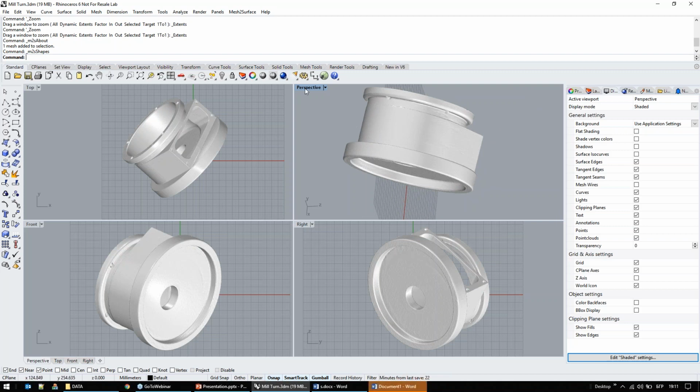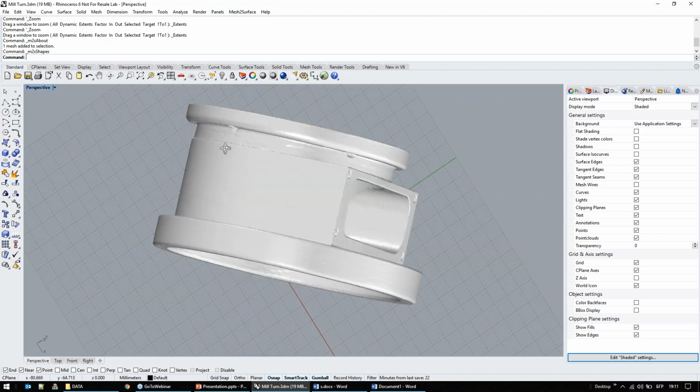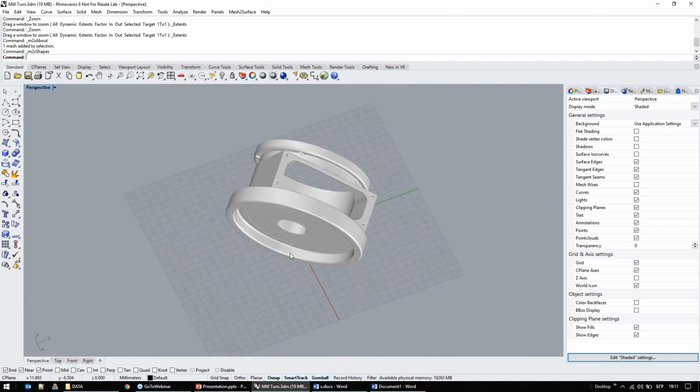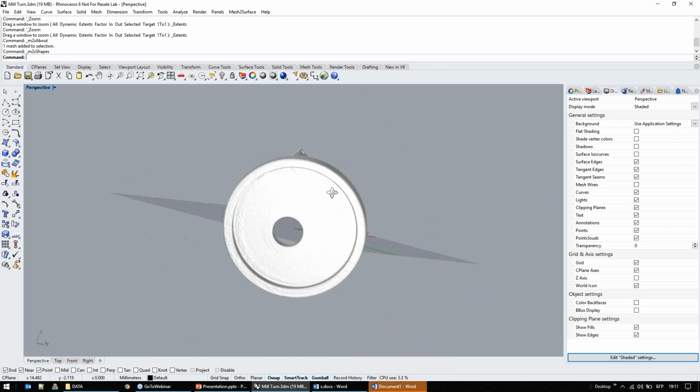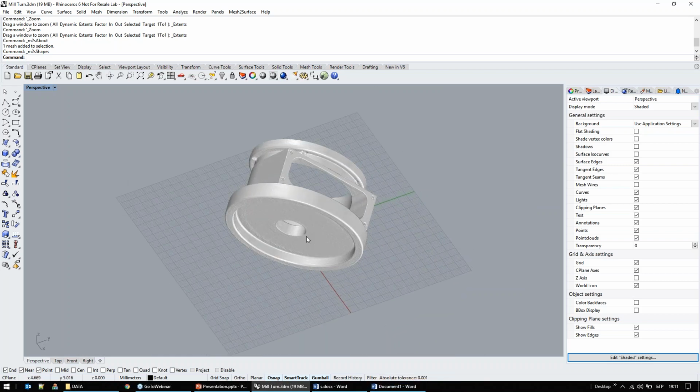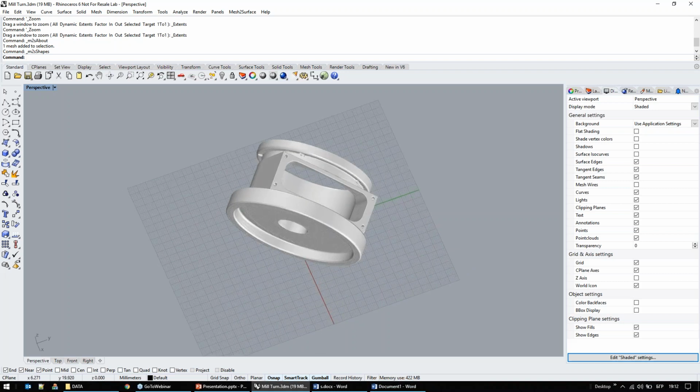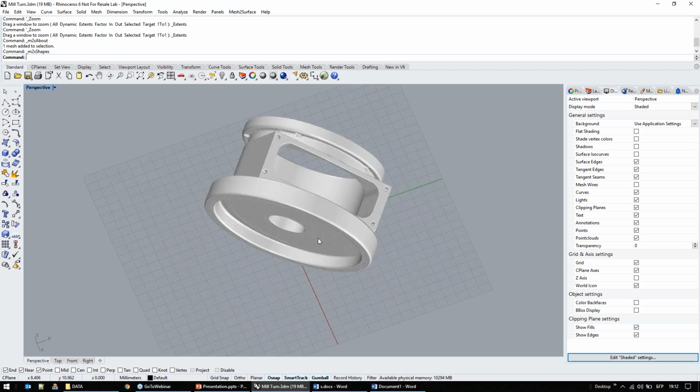So we normally get this type of shape, we put it in our environment, and the first thing we see is that it's not aligned. It just stays in space. If you're using a scanner like Faro with touch probing, you can do a datuming and align this object in space, but in other cases like Creaform, Artec, or any other non-contact scanners, it's really difficult. So they just give this object and say, okay, make a reverse engineering out of this.